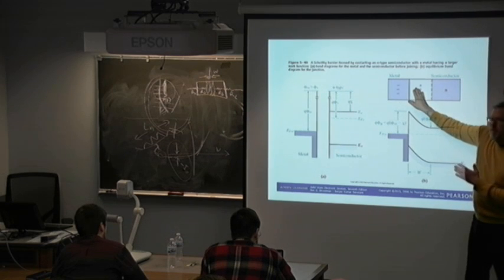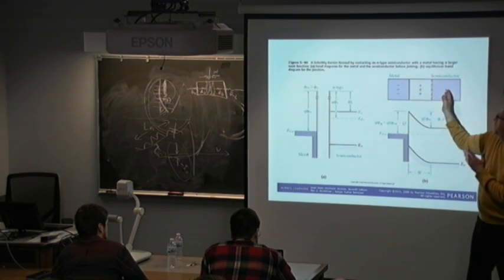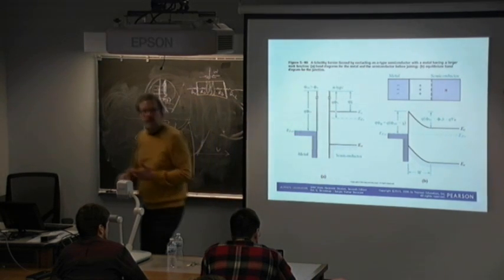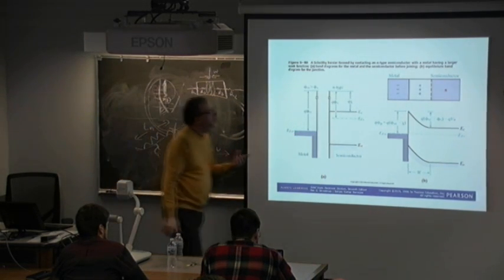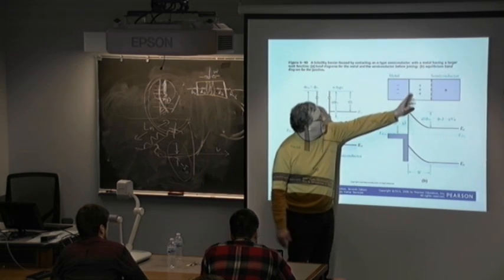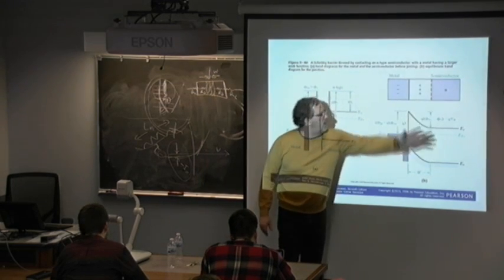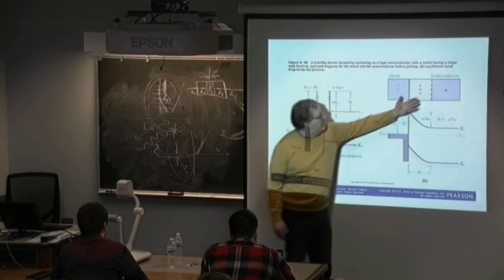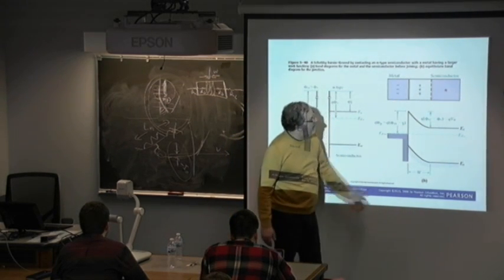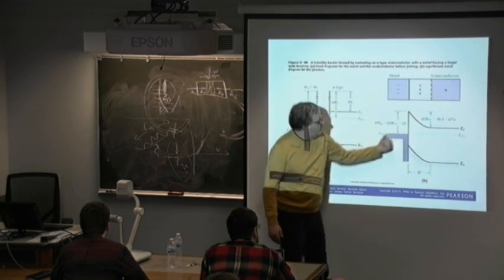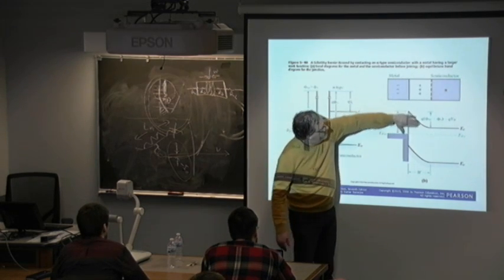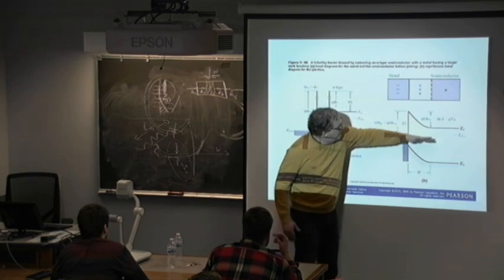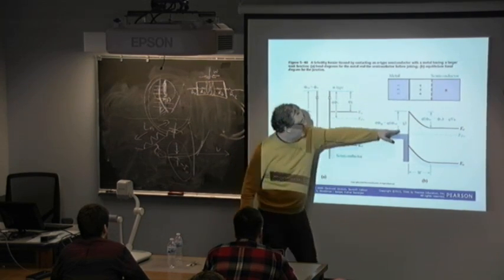Where did that charge come from? It's the ionized donors, because this is just a metal semiconductor junction. So I end up with this depletion region. All the electrons are swept away, revealing the ionized donors. So the positive charge associated with that pushes this down with respect to the metal. Then the bands distort and bend and establish equilibrium, and the Fermi levels align.